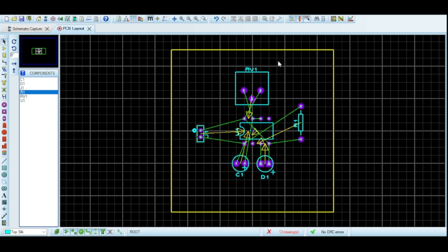We can begin routing, and we can set it to single and bottom layer, and maybe about 70 here. The style, maybe we can go with 13, default here. Let's just go with the default. I'm gonna choose the auto router as well.